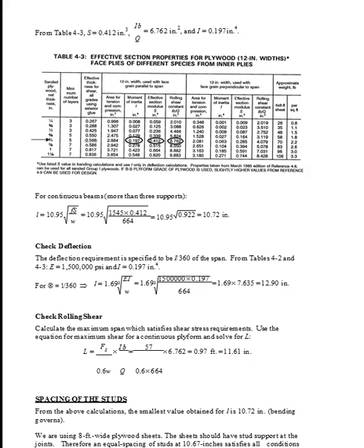Okay, and again, remember what's important about this. You need the strength to be able to deal with the material, but spacing of the studs is critical because the farther apart you can get them, the less material you need. So that's what's important. That's why I think, especially when you look at the programs, you can see how much quicker it is to be able to come up with a variety of stud spacings by varying material, thicknesses, size of members. And I think that's what is really important here, is to be able to look at some alternatives.